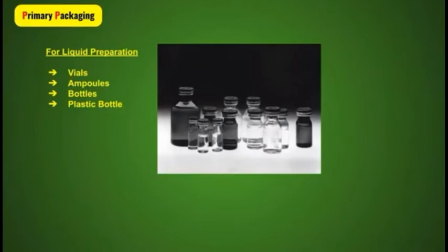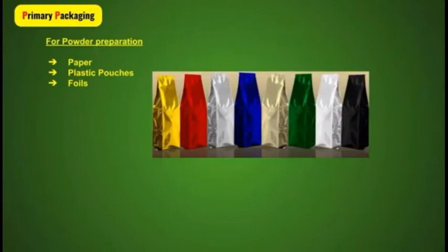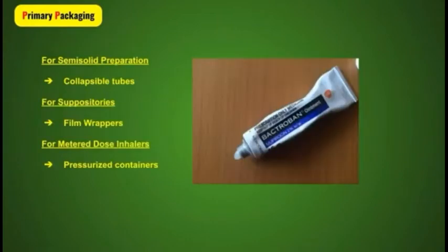This polyvinylidene chloride is also known as saran, or polychlorotrifluoroethylene, known as aclar. These films, saran and aclar, can be laminated to the polyvinyl chloride, and the moisture barrier of polyvinyl chloride with aclar is superior to that of saran coated polyvinyl chloride, especially under prolonged and extremely humid storage conditions. And the third one is strip packaging.